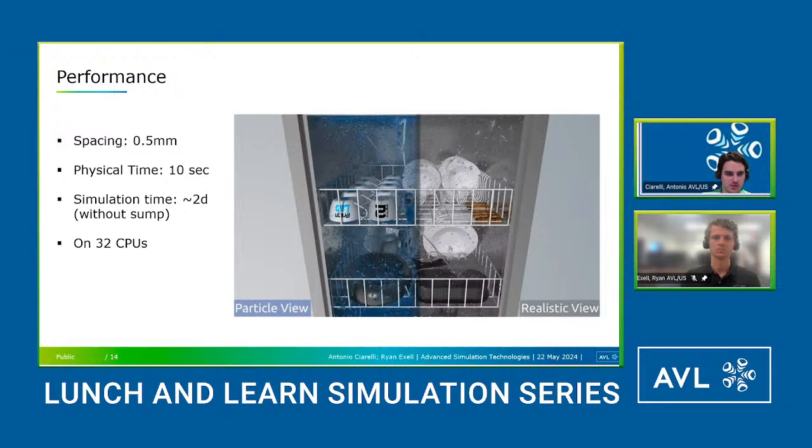With this specific simulation, we utilized 0.5 millimeter spacing with a physical time of 10 seconds for the simulation. And this took approximately 2 days to run on the solver on 32 CPUs. Now, this is not necessarily the most you could throw at a simulation. We utilize MPIs and GPUs, which Ryan will get into later in this presentation, to greatly increase the run speed and decrease the overall run time needed for each of these simulations.